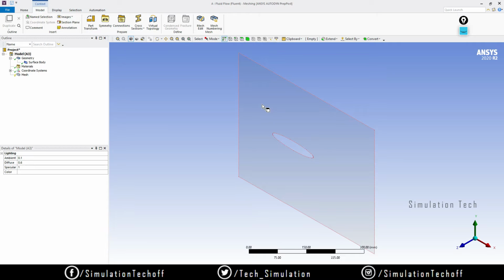So this CFD solver uses an iterative solver. Iterative solver means it solves the problem by iterations, n number of iterations, like 10 iterations, 20 iterations. If your problem needs to be converged, you should have a good and proper mesh. We will clearly explain what the iterative process is when we get into the Fluent model.